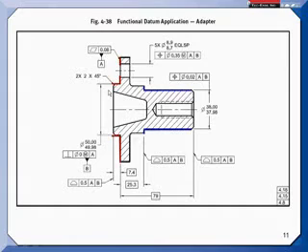See, I wouldn't tend to agree with you. If you look at this one, A is this face, and B is this diameter. Now, if I don't have a perpendicularity on B, the longer this thing gets, the more serious a perpendicularity error could be, because that means, let me kind of illustrate it here. This might come in exaggerated, something like this.